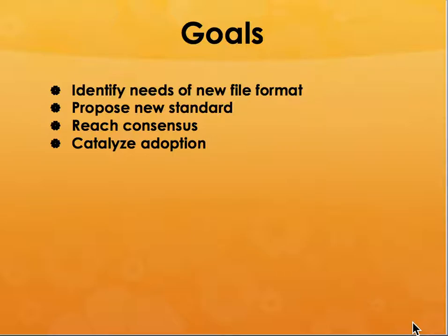One thing that people have done is they have tried to get away from the STL format, because STL is a really old format and it may not give you the accuracy of the parts that you want to build. So what people have been trying to do is to create a new file format that is compatible with every single 3D printing or additive manufacturing machine there is.